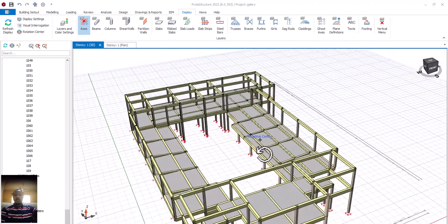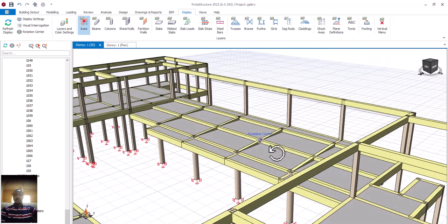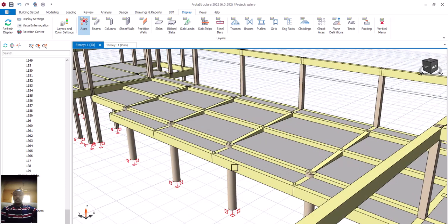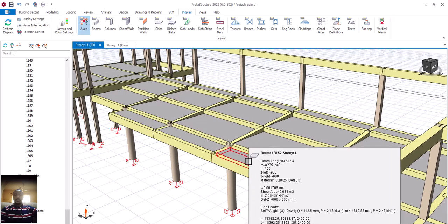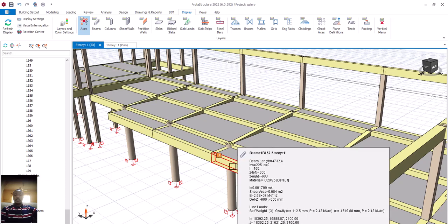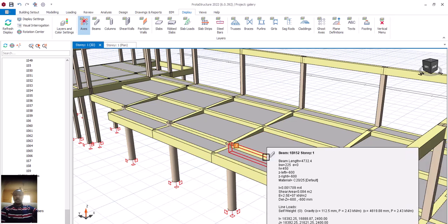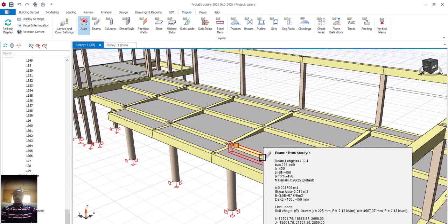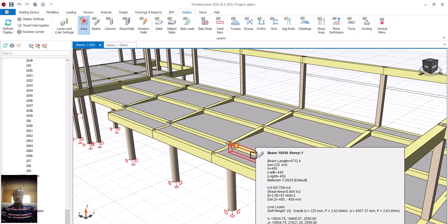So now there's something I want to explain. Looking at this place, this beam here, as you can see, is a drop-down beam for this slab at this point, where my cursor is now. But when it comes to this slab and this beam here, this beam for this slab at this edge becomes what? An inverted beam, in the sense that the slab is not resting at the top of this beam here. Is that okay?